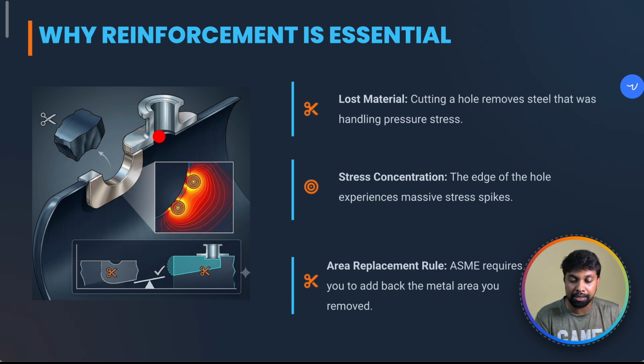Why do we need to compensate? We need to compensate because of stress concentrations. In the pressure vessel, most of the stress concentration will be on the edge of the opening. Here you can see. And also we need to compensate the material which has been removed.